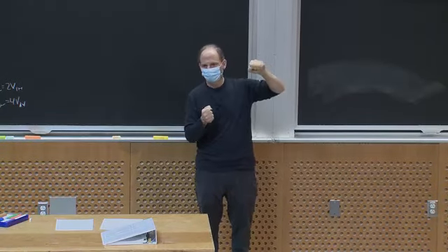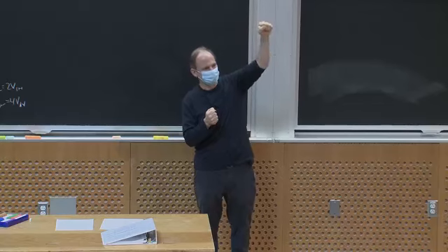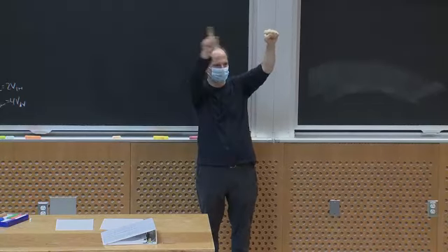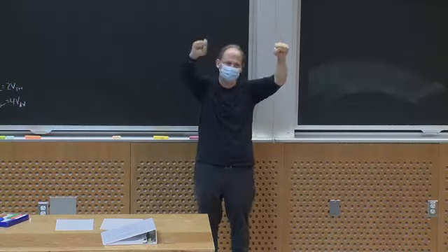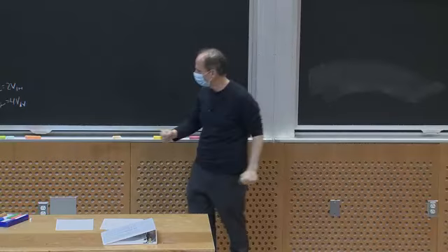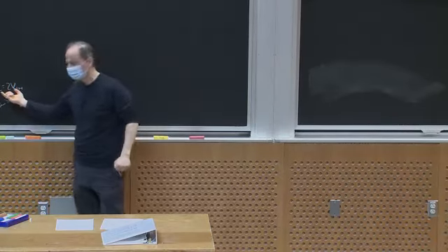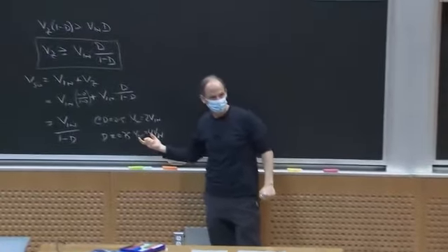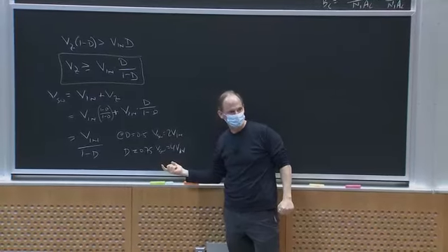Because in a normal buck converter, the switch is just blocking the input voltage and the diode is circulating in the second part. So it has the input voltage across it. Here, even at 50% duty ratio, I have twice the input voltage. It keeps getting worse at higher duty ratios.